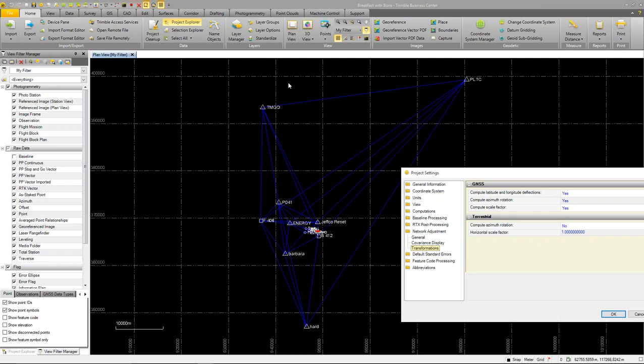When you go to start fixing coordinates for your points in the network, when you're doing your constrained adjustment, you can calculate rotations and tilts and scale factor for your network to fit with your control the best it can. So those are parameters that you can solve using the least squares adjustment.